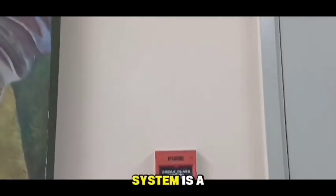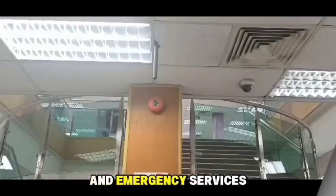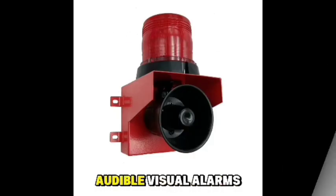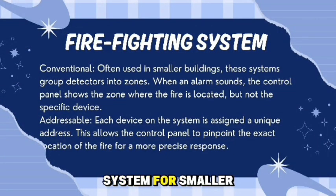A fire alarm system is a building system that detects fire, smoke, or carbon monoxide to alert occupants and emergency services. It includes components like smoke and heat detectors, manual pull stations, audible and visual alarms, and a central control panel that monitors the system and can even trigger suppression systems like sprinklers. There are two main types: the conventional system for smaller buildings and the more detailed addressable system for larger ones.